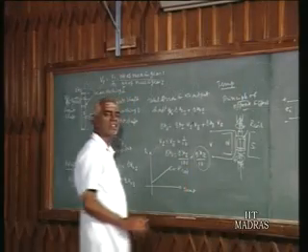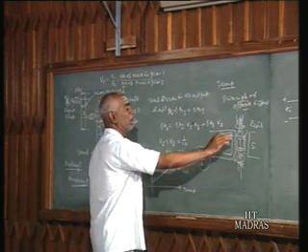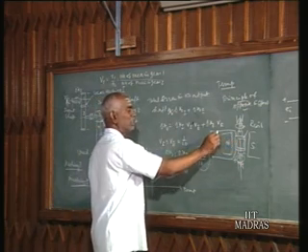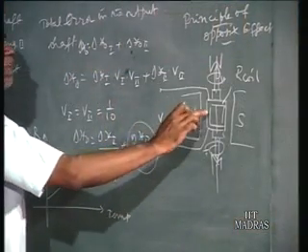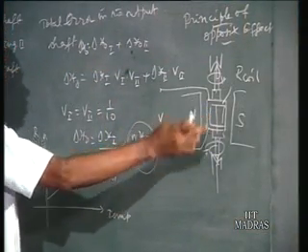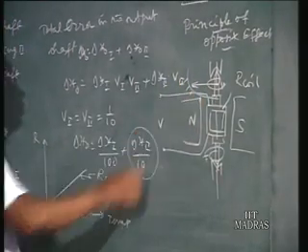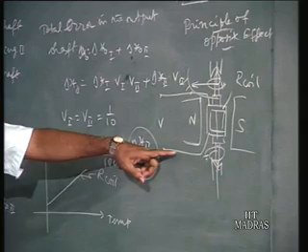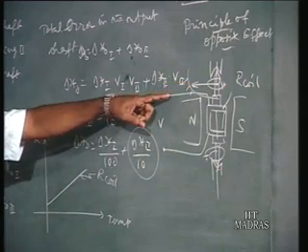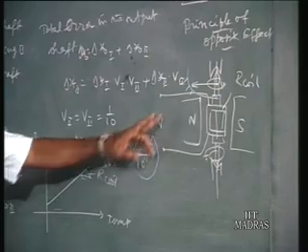For a given voltage input, we find that when R is increased, then the current through the coil is reduced. And when current is reduced, the torque is reduced, and then the deformation, that is the pointer motion over the scale, is also reduced. So for the same voltage, when temperature is larger, the amount of deformation of the pointer will be smaller. So that is the error due to temperature.